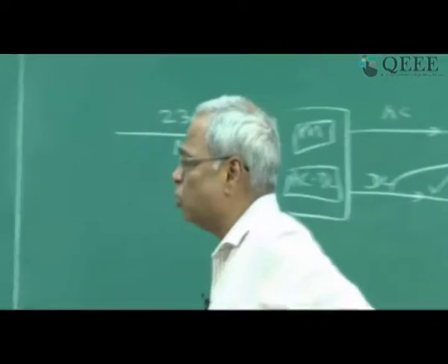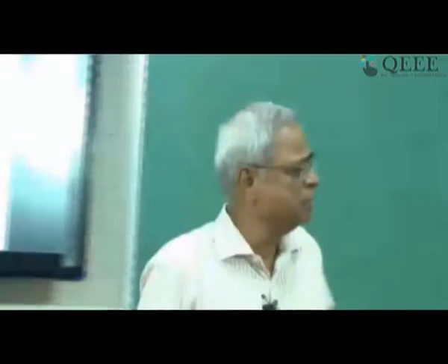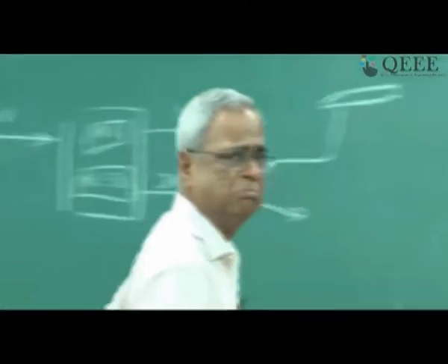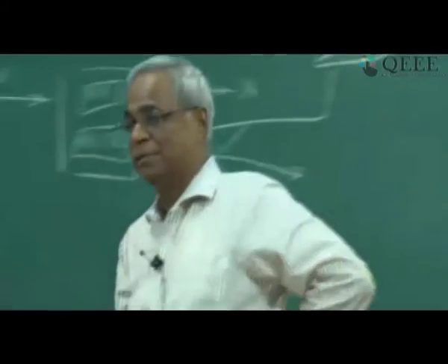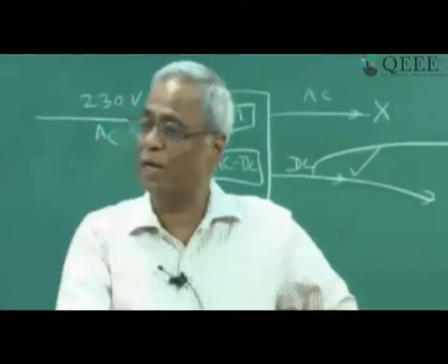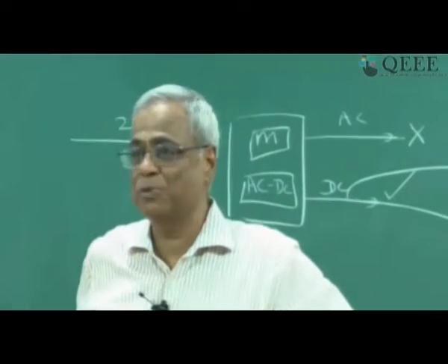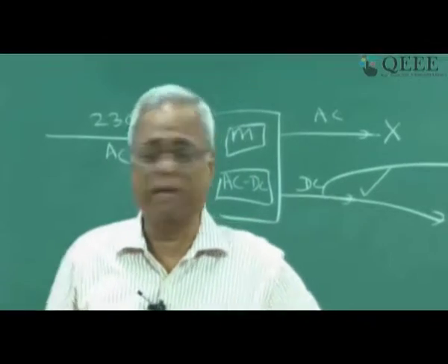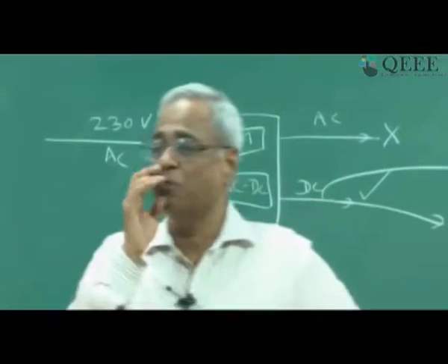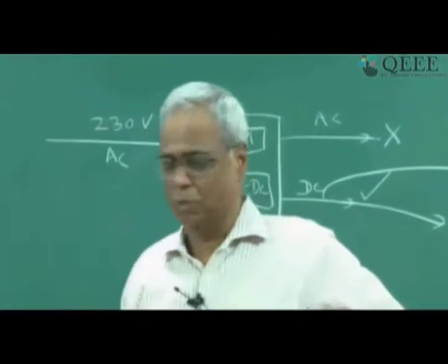What is a typical load shedding? Well, it varies. I have taken one case where the load shedding is only 4 hours: 2 hours during sunlight and 2 hours during off sunlight. So if the load shedding is there and solar is there, you can power from solar. What is the load usage? Well, again it will vary. I have just assumed here that during sunlight I assume 40%, and 60% of the load is during evening hours.